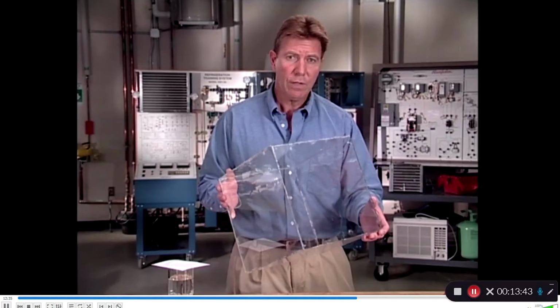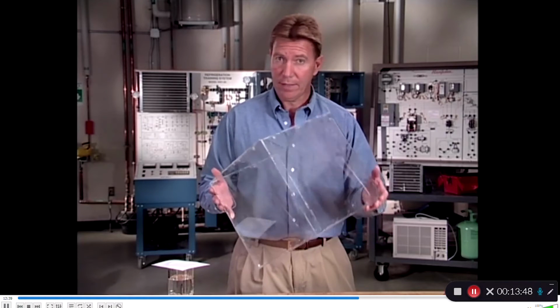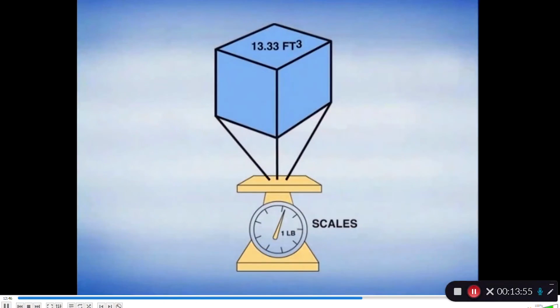Density is the unit that describes how much 1 cubic foot of a substance weighs. In the case of air, the density is about 0.075 pounds per cubic foot. The number of cubic feet required to make 1 pound of air can be obtained by taking the reciprocal of the density. The reciprocal of the density of air is 1 divided by 0.075, or 13.33 cubic feet per pound of air. This is referred to as the specific volume of air.